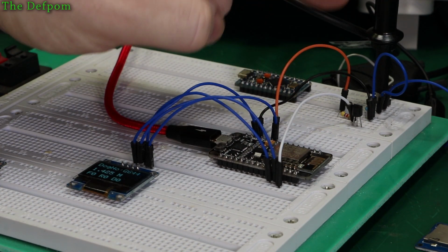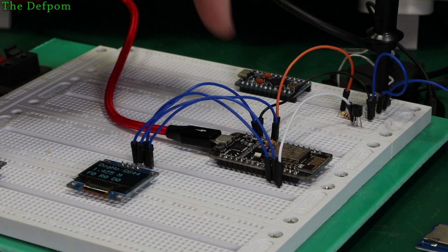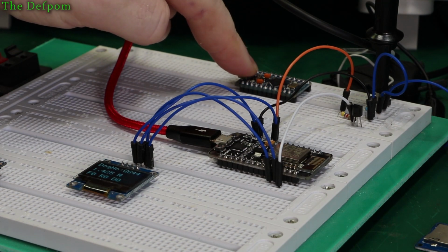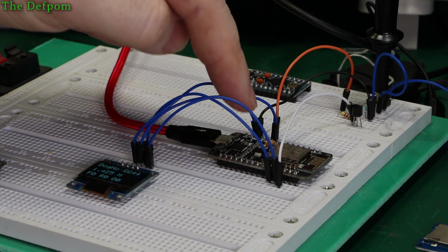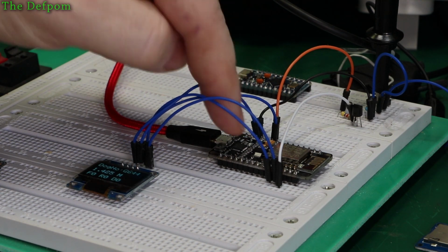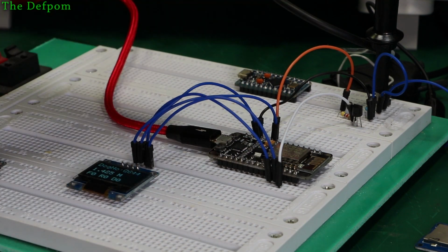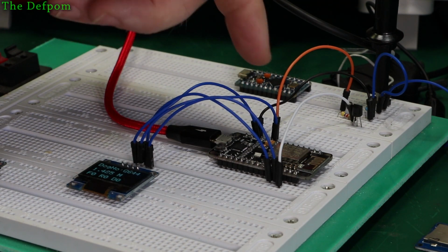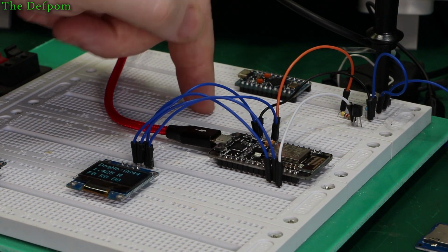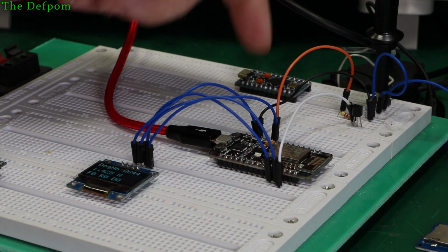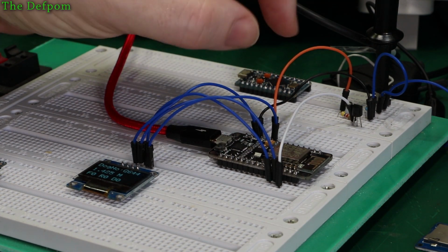What is coming in though is over 5 volts. Now the Arduino would be fine with that, it's only just over 5 volts, but the ESP8266 is only 3.3 volts, and if you put 5 volts into that, you're going to damage it. Using this level converter setup means this is safe as well, so I'm going to change the voltage level going to this level converter. Mind you, the Arduino will read 3.3 volts just fine, so I'm not too worried about that. It still treats it as a high state, so it works.